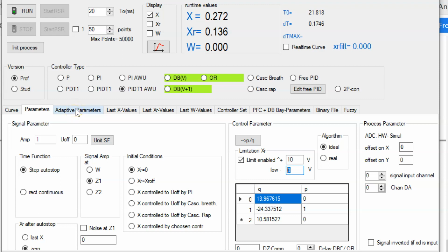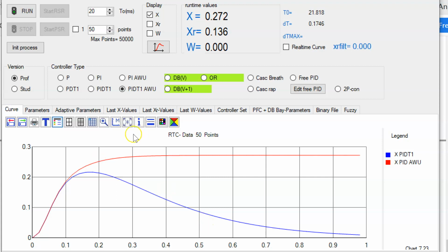So you can see you have to test your algorithms, the combinations of the algorithms, because sometimes you get problems with some combinations. I never have seen this. Sorry for this. That is new for me. So I'm astonished, but I can understand it and I can explain it. This is a case where we have to work a little bit on it. If we have heating systems and disturbance responses, be careful with the anti-wind up function.